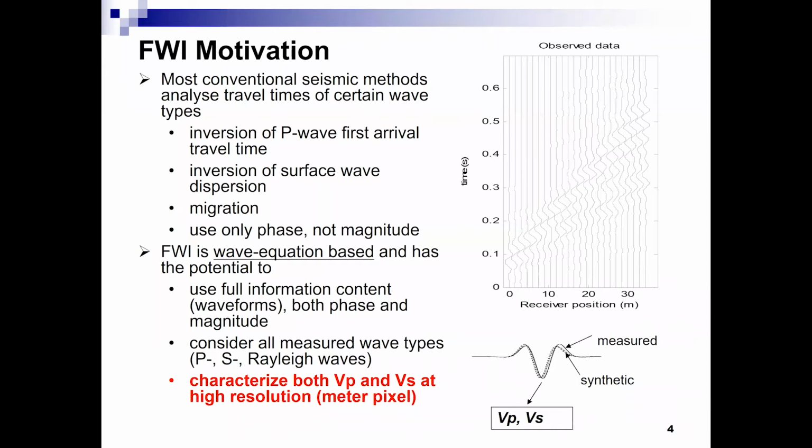So the horizontal axis here is the receiver position. That is a 2D problem. The vertical axis is the time domain. The signal that propagates through the void or soft material takes more time to travel and will show up as a later point in the measured data. So if we use only the first arrival signal, like refraction tomography, we miss the entire information of the void. We need the later points in the measured data to identify the void.